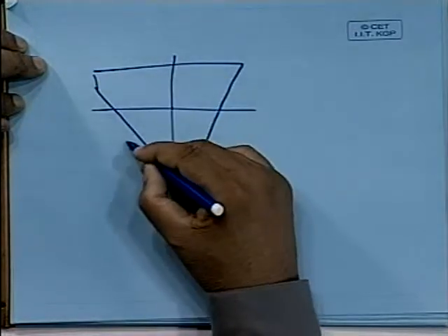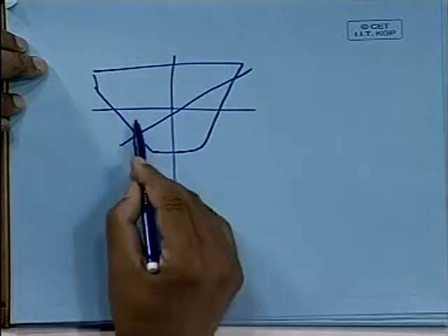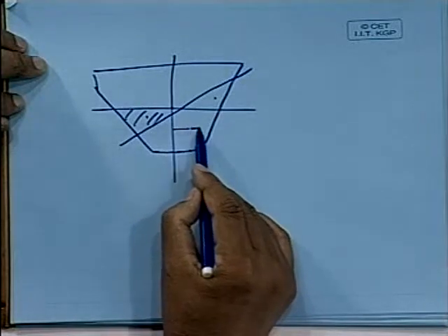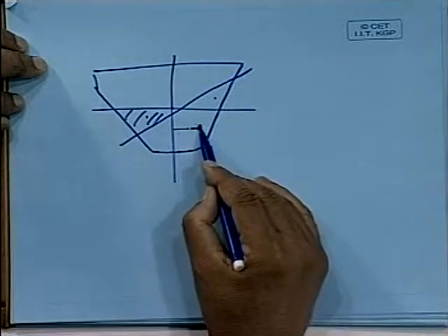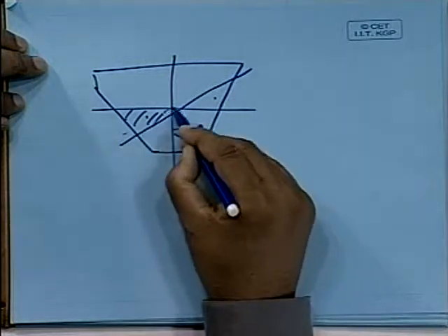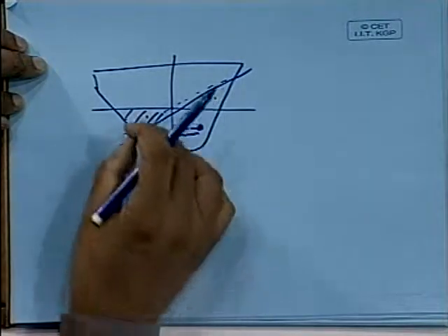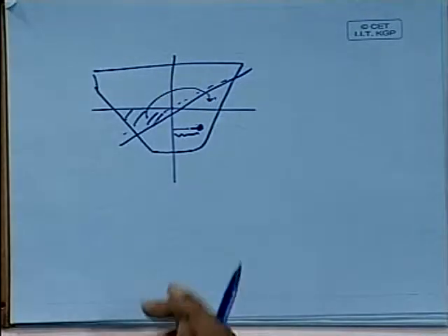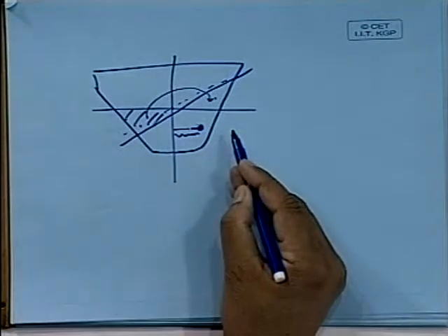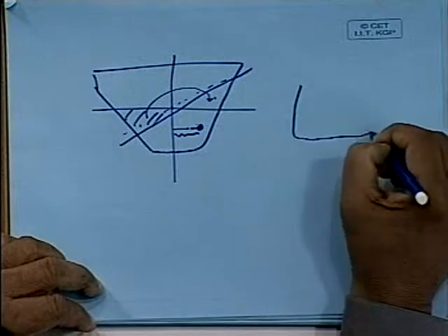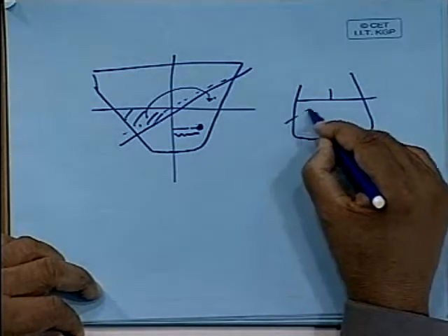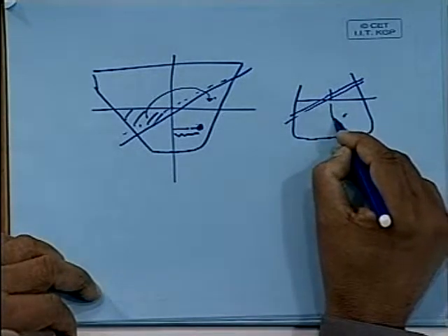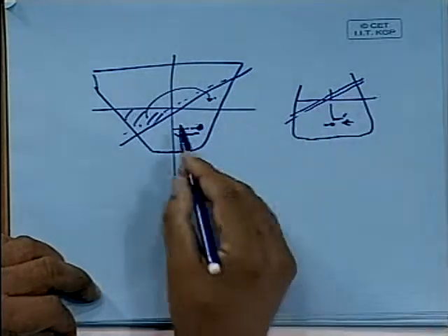Now what happened? When it goes up like this, you see, the center of buoyancy is removed this much here. So the buoyancy shifts more to this side. This part is larger than had it been through this. You are shifting this weight to a larger extent, as if you are taking this weight and putting it further on this side. If you consider the other case, say a hypothetical case, the water line will go actually like this. So the shift of B is lesser. The shift of B in this case is less than in this case.